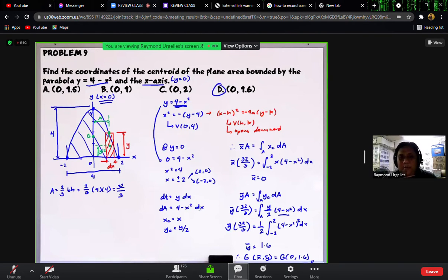In our figure, our base is the x-axis. So we know this is 2/5 of the height, which is the y bar itself, since it is on the x-axis. We know our centroid is on the y-axis because it is on the axis of symmetry. So we immediately know that x bar is 0. Therefore, using the direct formula, x bar is 0, again because this is the axis of symmetry.